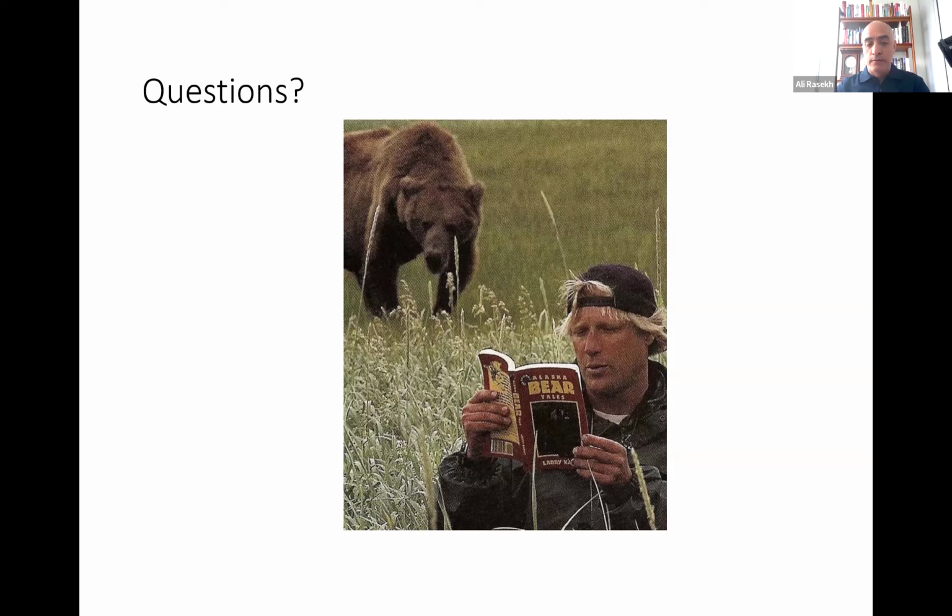For verification, we have a lot of different strategies depending on how much budget we have, but one of the best is what I call progressive analysis. We analyze at different levels of complexity or with different assumptions, similar to what I tried to show you very quickly: how two solutions compare, one with engineering judgment, which is the massless foundation, the other more physically sensible, which is the mass foundation.